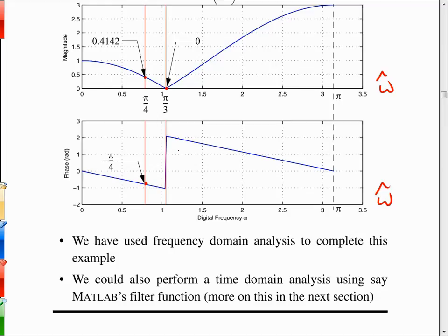And then other frequencies of interest might be 120 hertz because a lot of times the second harmonic shows up too. If we have a 60 hertz signal present and we have some nonlinearity or some other processing going on in the electronics, it's very easy to get the second harmonic, which would be the 120 hertz. So you might have to deal with that too.